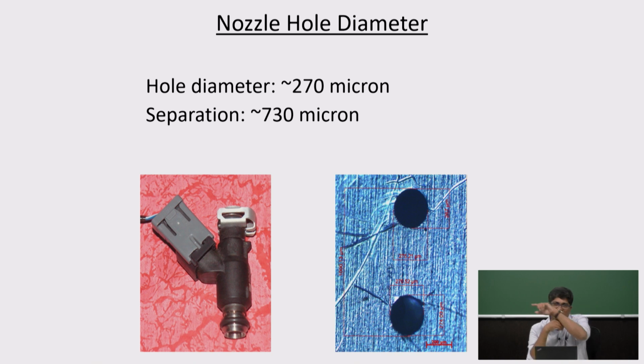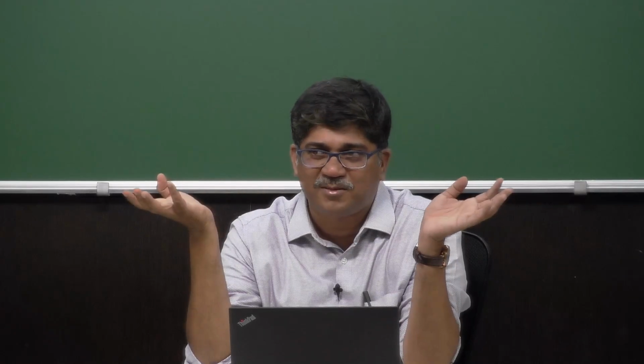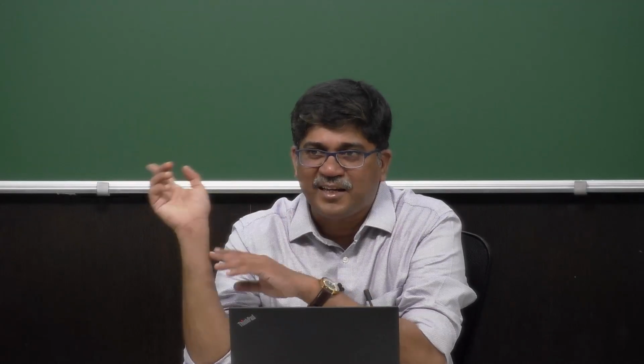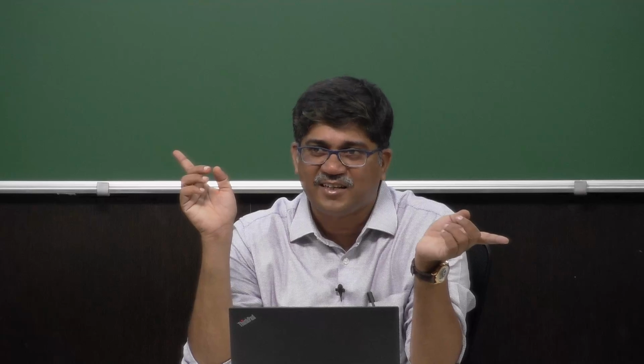So if my mass flow rate is constant, m dot will be equal to rho (density) times area times velocity, because liquids are incompressible or nearly incompressible, so we will not have much change in the density. So if I increase the velocity, I have to reduce the area. So you need to use small orifices, so small that they will be of the order of 50 micron. With the naked eye, it will be difficult to distinguish them.